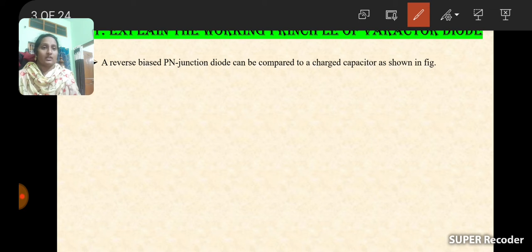And how can we protect our circuit from these disturbances? Those are called remedies. What are the remedies to produce stable oscillation? First problem is power supply variation. So without variations, how can we get the power supply? By using a regulated power supply. By using a regulated power supply, we can produce stable oscillations.